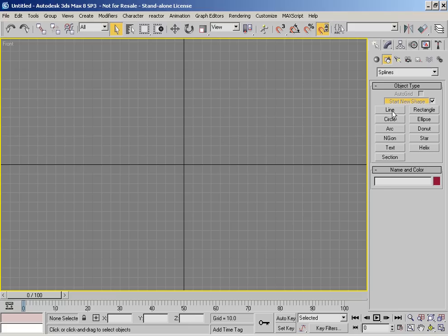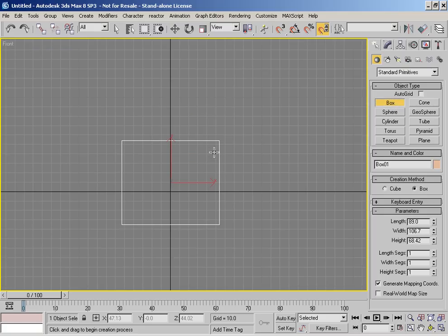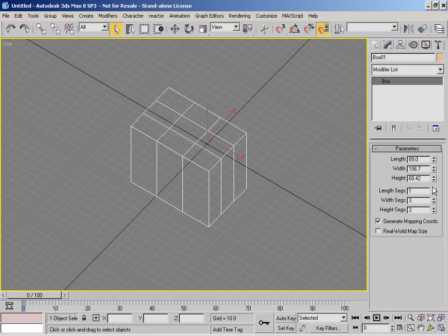As with all types of modeling, we don't want to mix quads and tris together. In essence, what I'm saying is don't have triangular faces mixed with square or rectangular faces, because if we come to mesh smooth or refine later on, we're going to get some nasty pinching in the geometry, which looks like the geometry has been put through a grinder. Case in point, let me quickly create an object here, and I'll give you an ideal example of what this problem looks like.